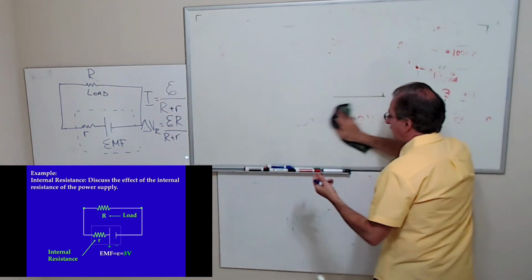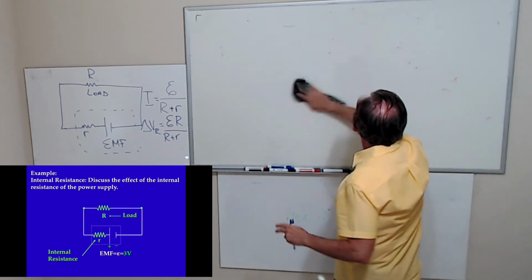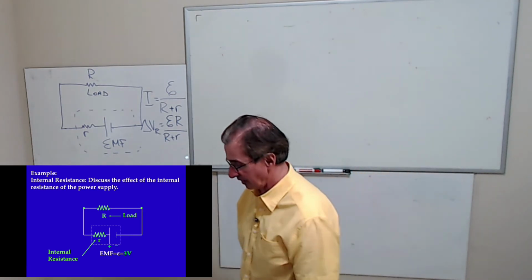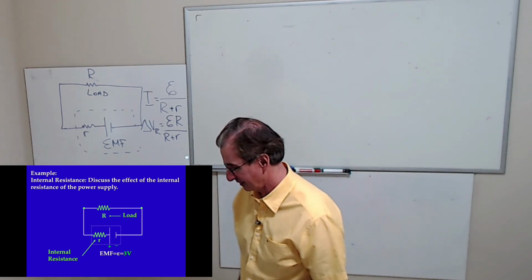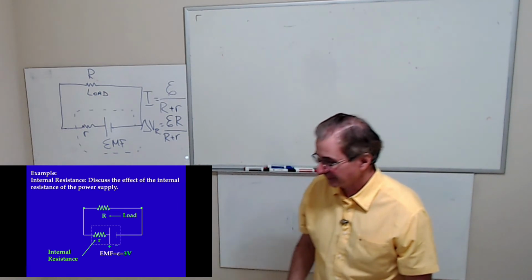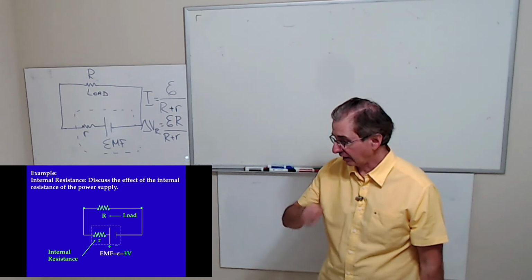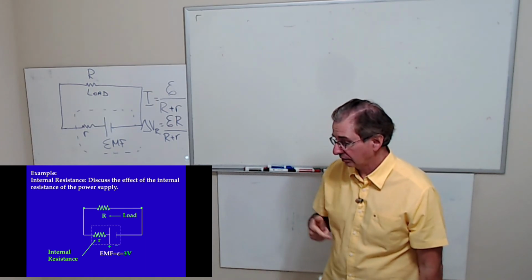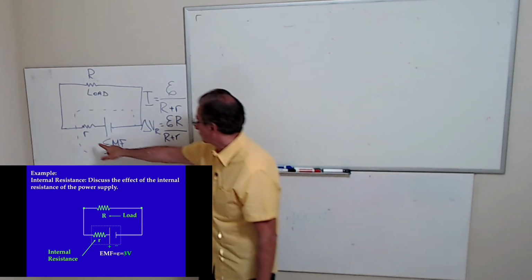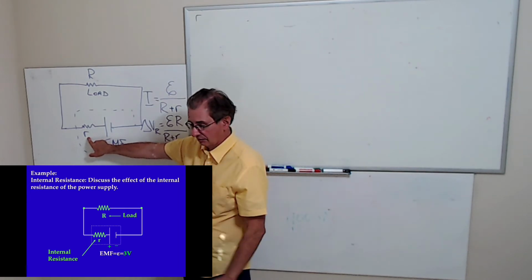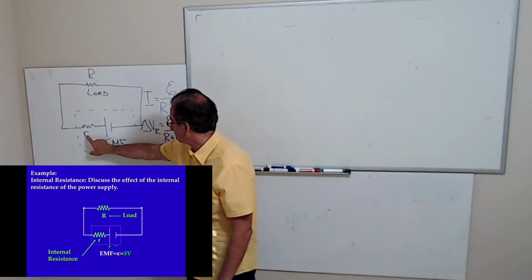And what is the effect of the internal resistance? If you have a big enough current, you can see the effect. So if you go in your car, turn the headlights on, and then if you have a gas-powered car, I haven't tried it on an electric car, you turn the key. I guess you would see the same thing in an electric car. You turn the key, and now you're running a lot of current to start up the car. The voltage across the internal resistance will be much higher, and you'll see your headlights dim. That's the effect of this.